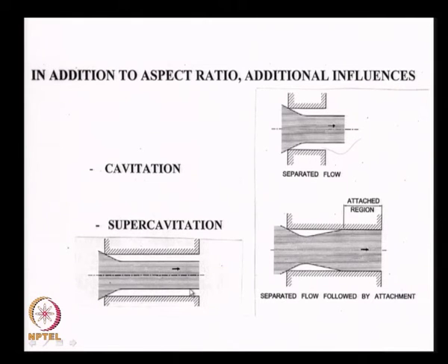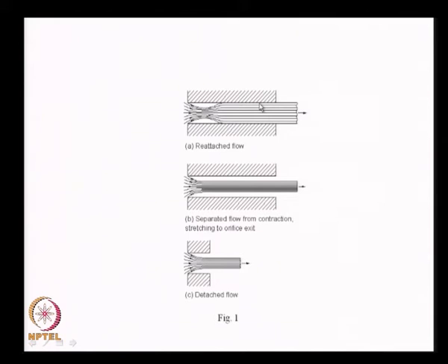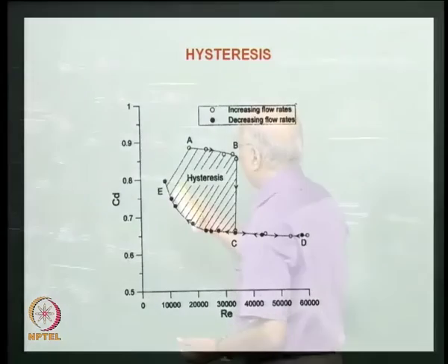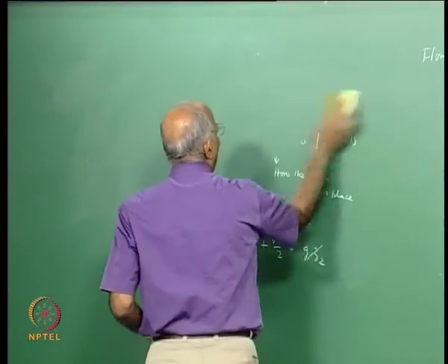Therefore, essentially we talk in terms of three types of flows: reattached flow when I have long length to diameter orifices, a flow which is separated when I have high velocities or cavitation taking place, and for small length to diameter orifices I could have separated flow. Therefore, I could get three values of discharge coefficients accordingly. If I do an experiment, I start at a low Reynolds number wherein I get an attached flow, for which, since it is attached, the whole flow area is contributing to the flow, and therefore I get a high value of discharge coefficient. Somewhere cavitation starts, it begins to separate, I go over here, it is still separated, and now when I start reducing the pressure or the velocity again, it goes like this, but the memory of the separated flow lingers on and CD decreases, it never comes back to this. That means even a small thing like a showerhead injector, which is nothing but an orifice like this, is not that straightforward. And what happens? Let's try to put this down.